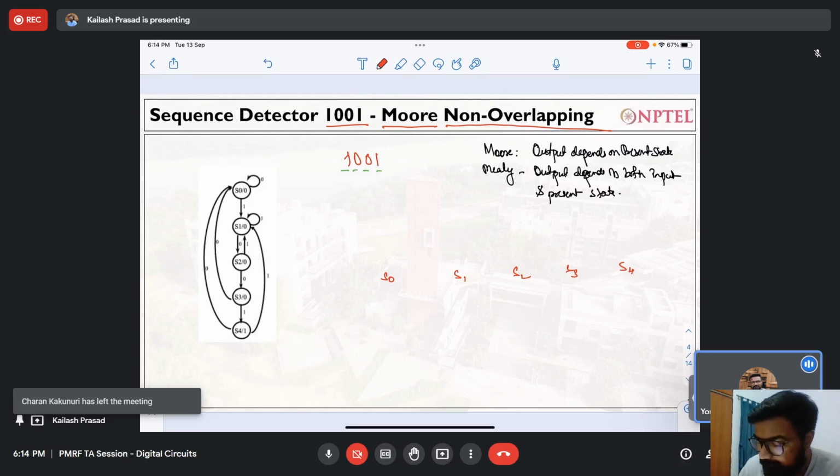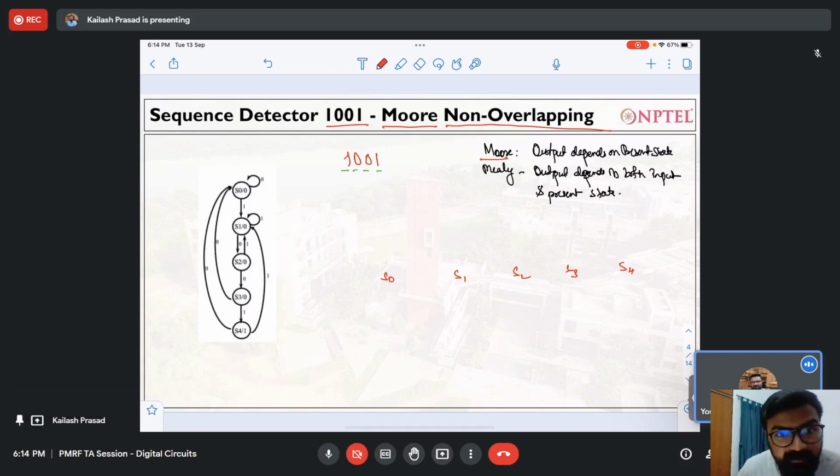These are five variables, and I have to define the output in the state itself. Why? Because for a Moore machine, the output will only depend on the present state, right? So if you know the state, you know the output. Only the final state will give me the output one. It means the sequence is detected. Otherwise, the sequence is not detected. So for this, the output will be one. For this, the output will be zero, and this output will be zero. For this, the output will be zero, and this also I have to define. So I've defined five states with their outputs.